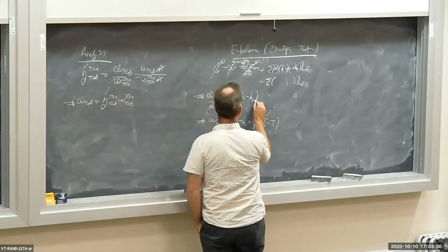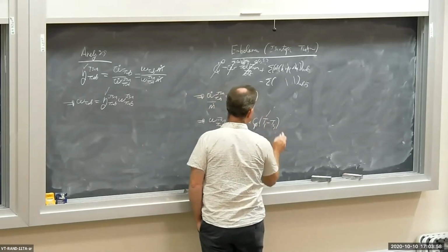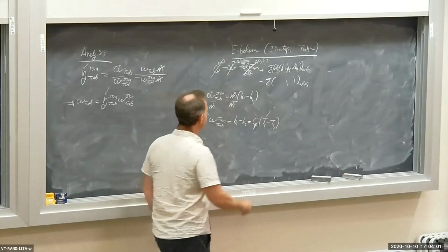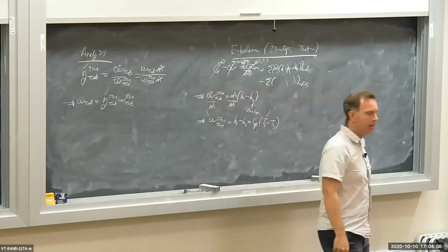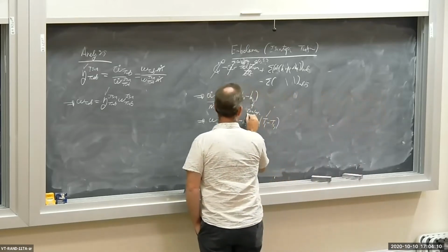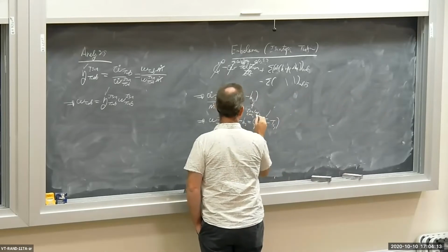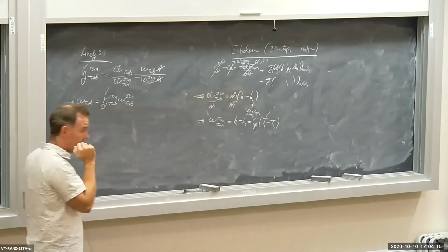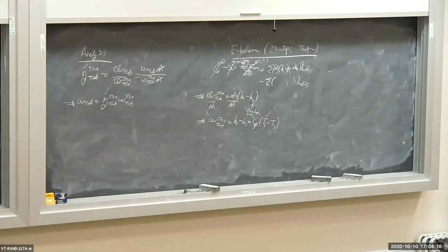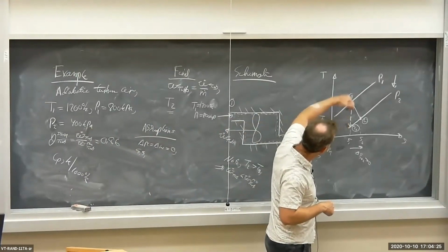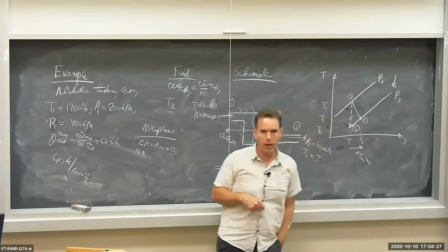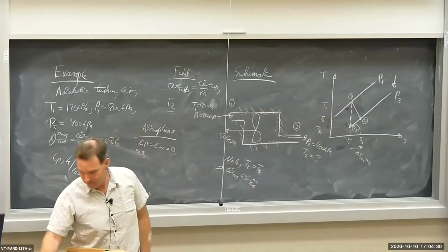So put a little s here and put a little s here. Isentropic. s1 equals s2 sub s. Again, look at your TS diagram. For the isentropic device, we're going from state 1 to state 2 sub s vertically down, and s1 is equal to s2 sub s.